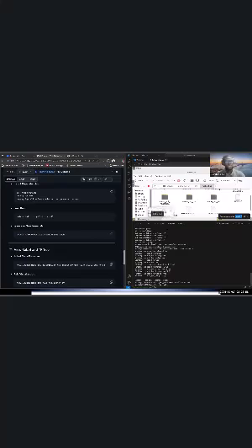He explained it very clearly. So the robot has a geometry, and different sensor components attached to it: the camera sensor, the lidar sensor, the tires. There's a base link and there are joints. The transformation has to keep track of the robot geometry and the different connections to the robot. We're going to visualize this. It's going to be interesting, guys. We're about to make our first visualization.